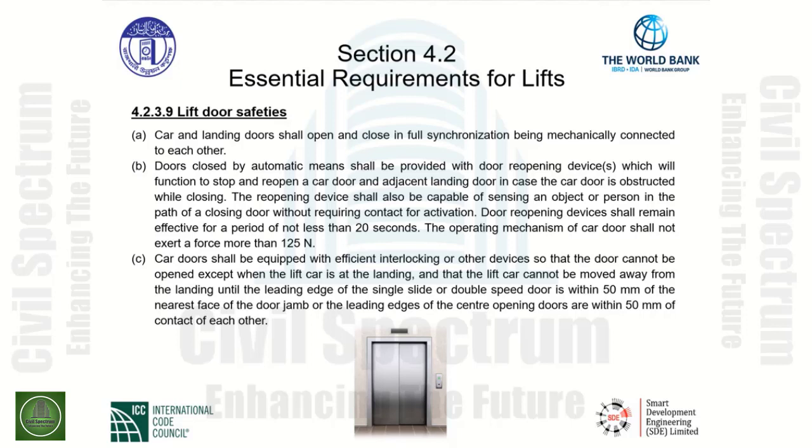Finally, item C, car doors shall be equipped with efficient interlocking or other devices so that the door cannot be opened except when the lift car is at the landing, and that the lift car cannot be moved away from the landing until the leading edge of the single slide or double speed door is within 50 millimeters of the nearest face of the door jamb, or the leading edges of the center opening doors are within 50 millimeters of contact of each other.